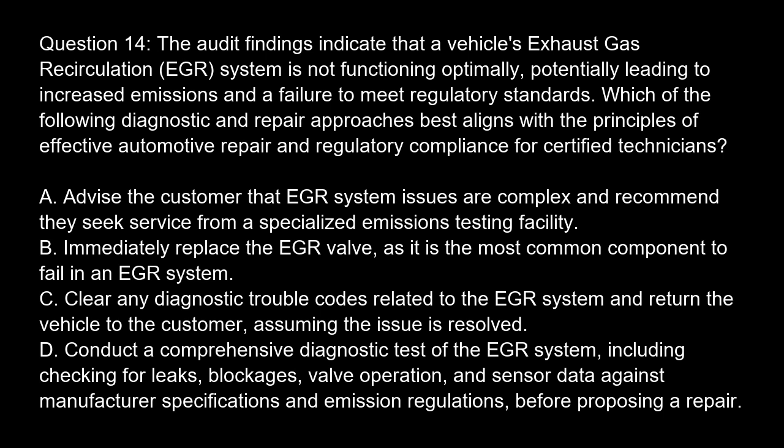Option A. Advise the customer that EGR system issues are complex and recommend they seek service from a specialized emissions testing facility. Option B. Immediately replace the EGR valve, as it is the most common component to fail in an EGR system. Option C. Clear any diagnostic trouble codes related to the EGR system and return the vehicle to the customer, assuming the issue is resolved. Option D. Conduct a comprehensive diagnostic test of the EGR system, including checking for leaks, blockages, valve operation, and sensor data against manufacturer specifications and emission regulations before proposing a repair.